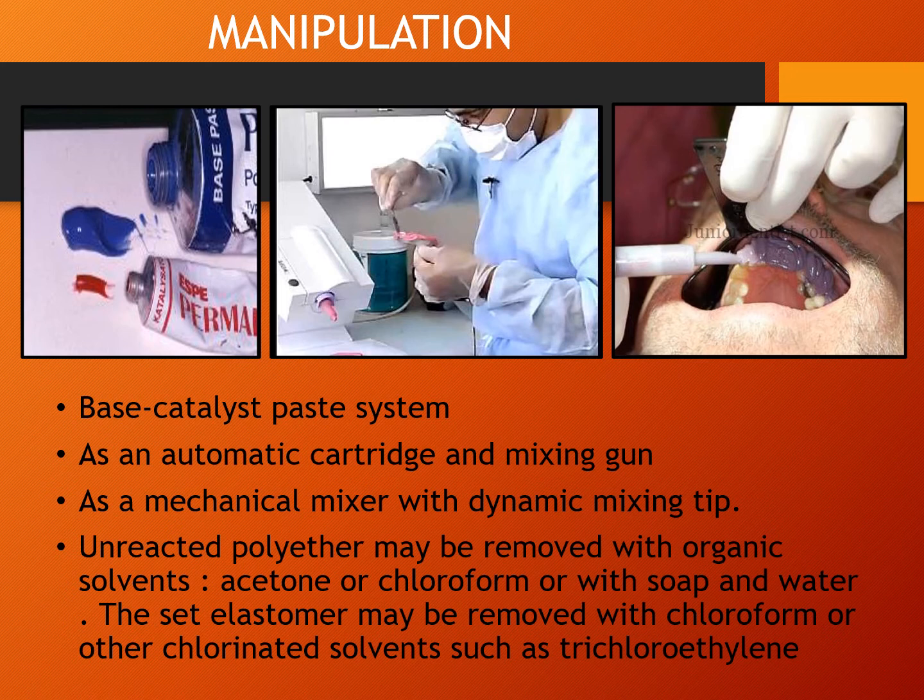Now we have already said that tubes of thinners will be available, which increase the working time and flexibility. So in such cases, an equal length of thinner should be mixed with base and catalyst, and this results in increased working time and increased flexibility.